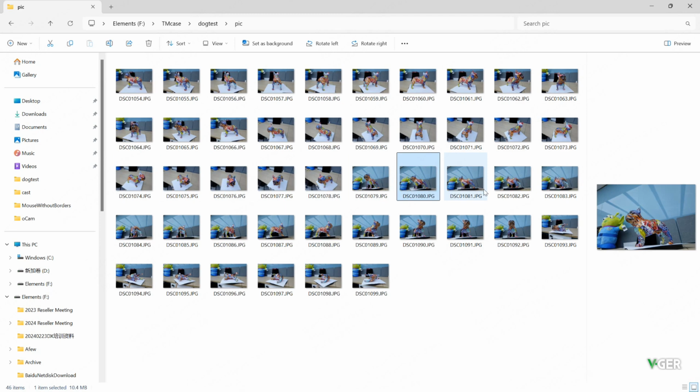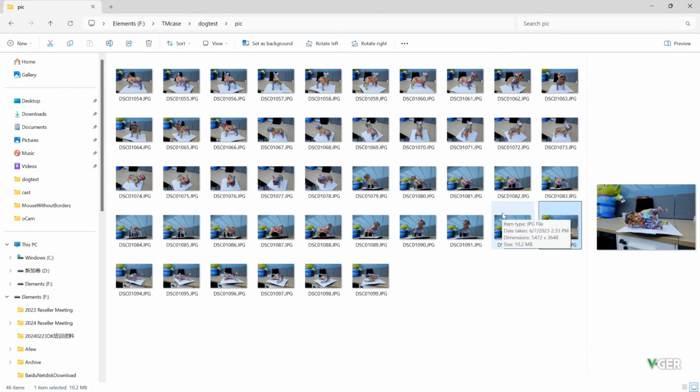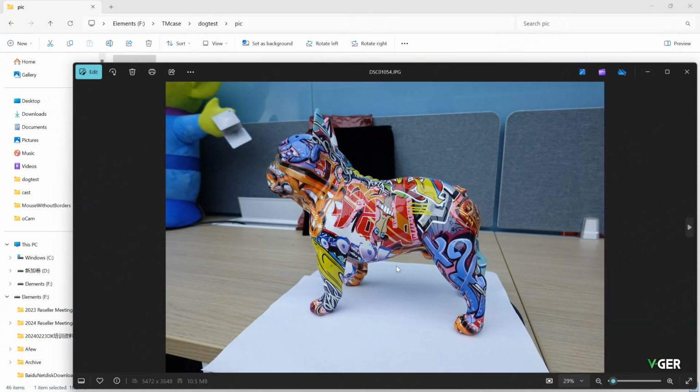for a couple of different angles: above, horizontal, and if you want the bottom as well, you might also take it from the bottom. Make sure each picture is in a sequence and they have enough overlap, okay? Another thing is, when you're taking these pictures, make sure the object is in the right middle of your pictures, and make sure it's large enough. Okay, don't make it too small, and this should be good.